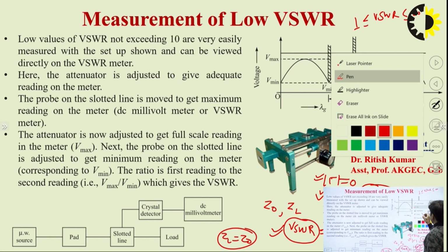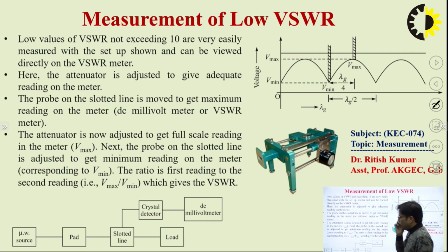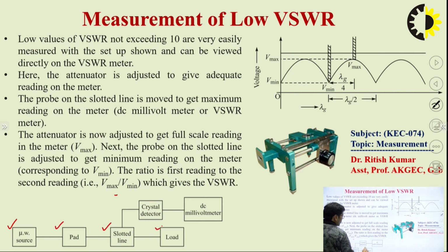Before starting to measure the VSWR, we need to understand what VSWR is. I hope it is clear to all of you what VSWR is and how we get VSWR in the transmission line or waveguide. So, here you can see the measurement setup. In the measurement setup we have the microwave source, pad, slotted line, load, crystal detector and DC voltmeter.